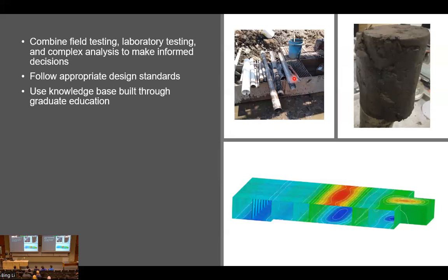Now, after collecting samples from the field, you sometimes had to take them to the lab to perform additional testing to get strength parameters relative to your analysis. So here I'm showing you an unconfined compression test sample. This is actually a soil cement mix, and for these kinds of samples, unconfined compression is a typical test procedure.